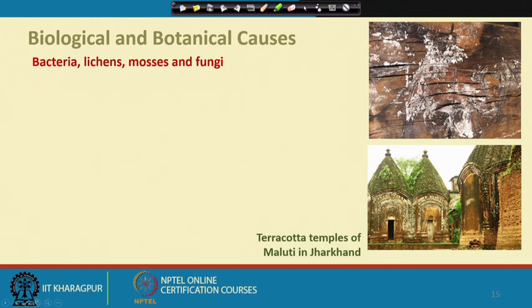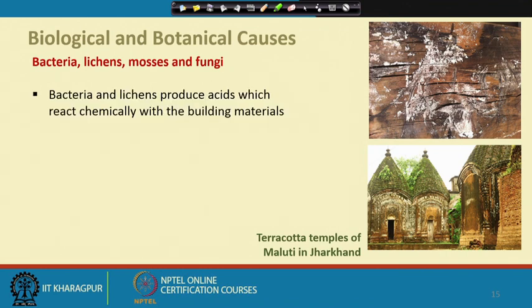the timber surface. As I say, these mosses, fungi, lichens and bacteria have various species, categories and types, and each has its own favorable habitat and environment, and their remedial measures also vary. Until we specifically know, we need expert advice depending on which type and which species. It can be tested, and they have spores, and these spores can lie dormant for some time and, depending on the environmental conditions, they can sprout again. So I will just give a brief introduction to this category.